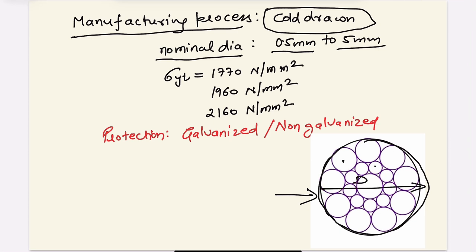But in actuality, the nominal diameter works on paper only. When the real wire rope sling is manufactured and we measure its diameter, it will be slightly above or below the nominal diameter, because there are some tolerances. That is called the actual diameter. The nominal diameter is the diameter that is mentioned in the drawing.